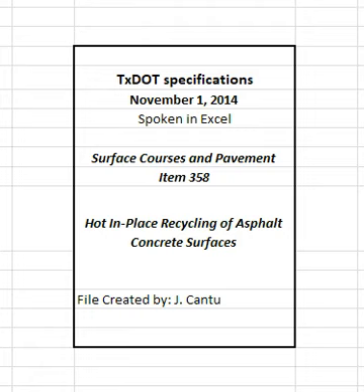Table 2. Operational tolerance and minimum testing frequency. See table in specifications. 1. Hamburg values must not exceed 12.5 mm in 10,000 passes, unless otherwise directed. 2. Compare with sample from mix design to determine amount of stripping. 3. In-place air voids should be between 3.8% and 8.5%. 5.4 Total asphalt binder content. Adjust the asphalt recycling content based upon mix design recommendations for varying roadway conditions to meet the requirements in Table 2. 6. Placement acceptance. 6.1 Placement lot.